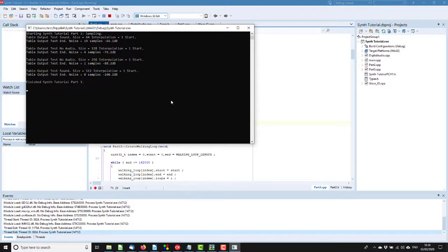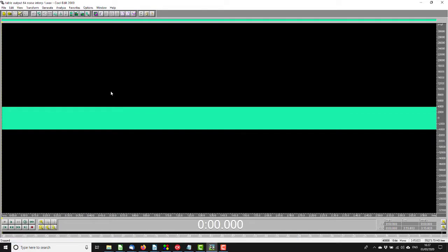So as you can see, if we use tables of 512 samples, the noise due to interpolation is less than the quantization noise, which is minus 96 dB. Now I thought the noise generated from interpolation would be heavily frequency dependent, but it turns out it is not. This sound file is the noise from running the 64 sample table test. I've multiplied the noise values by 100 so we can hear them and see them, and as you can see the amplitude of the noise remains constant as the frequency sweeps up. As I say, I didn't expect that at all.